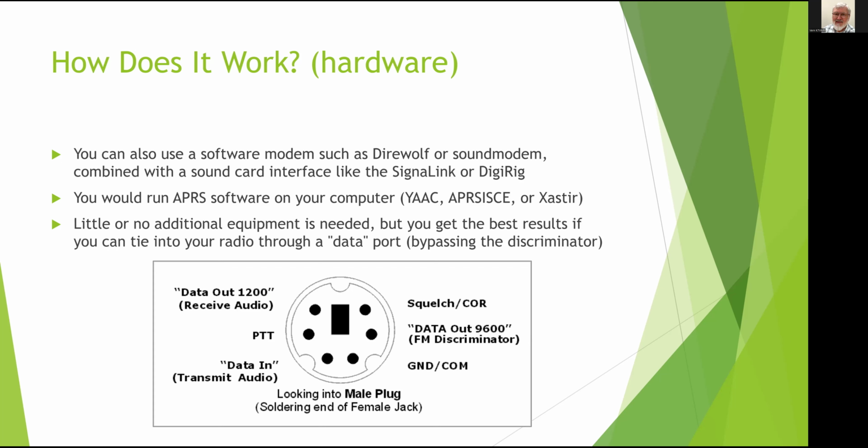I've seen people directly plug their speaker and mic ports on the radio into their computer's audio jack. I don't recommend doing that because there's no isolation if you do that. It also requires using Vox, and you have to set the radio for Vox because there's no PTT control that way.